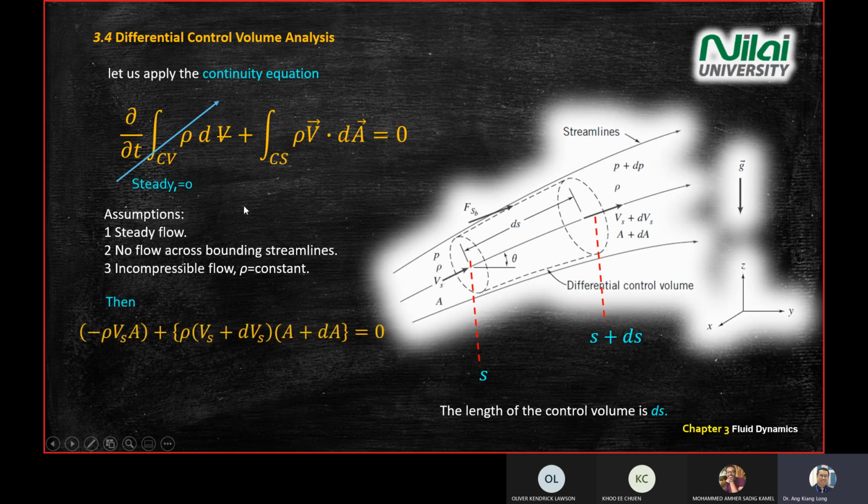So the next one, you look at what happened in the control surface. When you look at this equation, you know how we get it already from the vector form, v dot dA. You look at this section. Area is always positive, pointing to the left in this case, and then you multiply by the vector direction, you get negative.